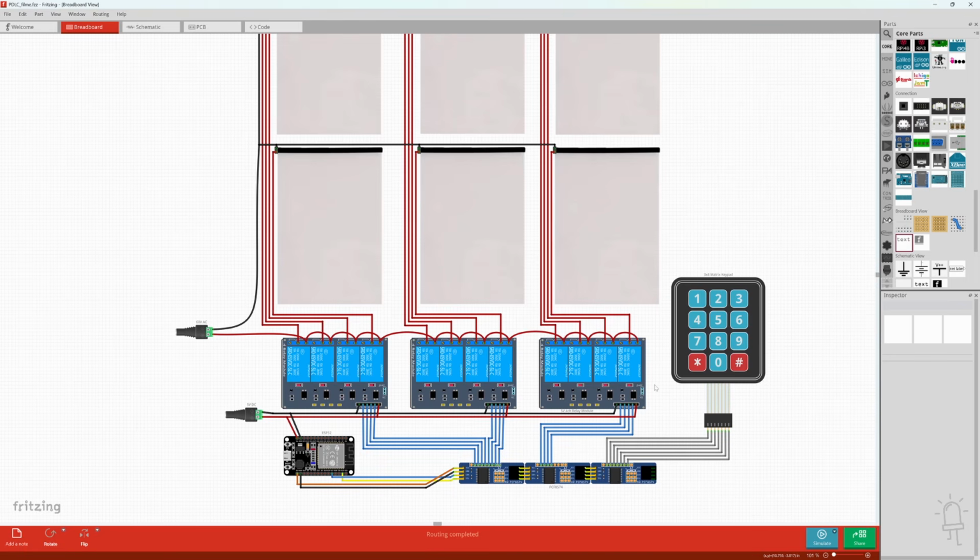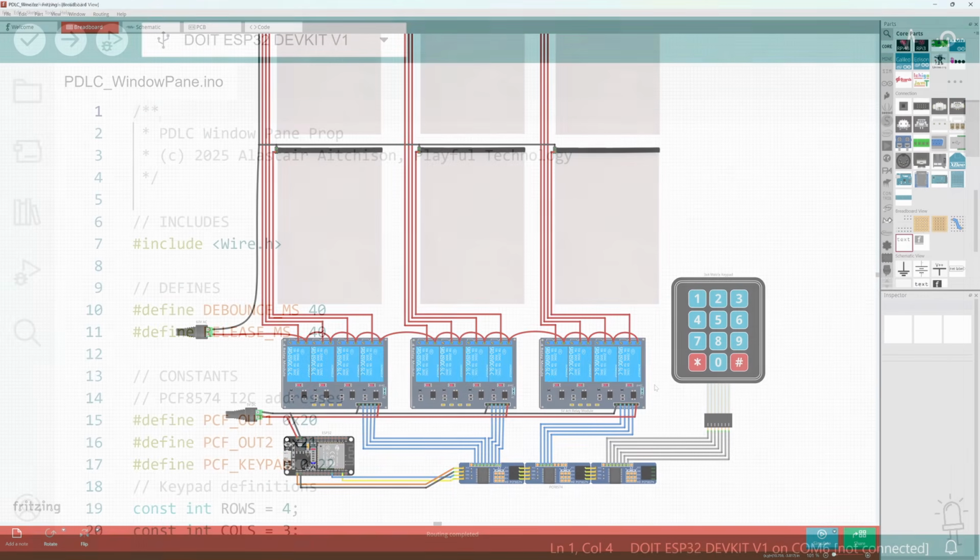If you had 1 meter square of PDLC film, that would only draw about 0.05 amps of continuous current, or 50 milliamps. And as long as you're using a properly current limited power supply to that film, that should be perfectly safe. But nevertheless, you should ensure that your wiring is secure, that players don't handle exposed contacts or any other part of the circuit, and that you use an appropriately rated power supply.